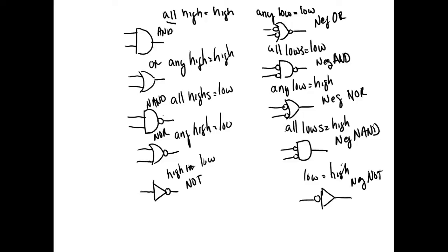But this is important right here, because now we can show y'all. Over here, if I did the Boolean equation on this, I'd say X, and then A and B, right? You understand? What would we say here? X equals A or B. What would I say right here? X equals A and B, and then I put a bar above it.